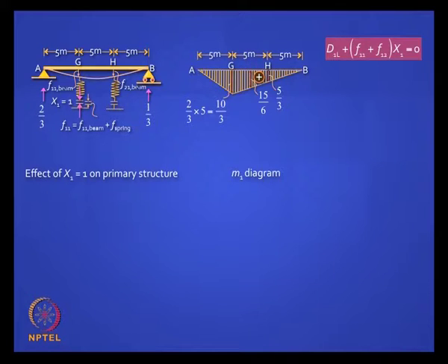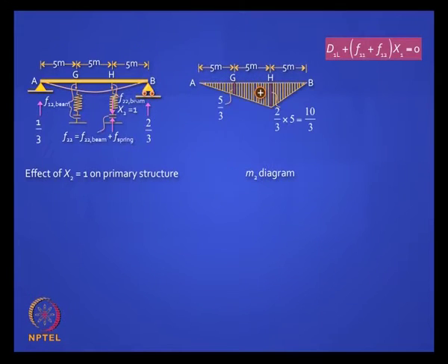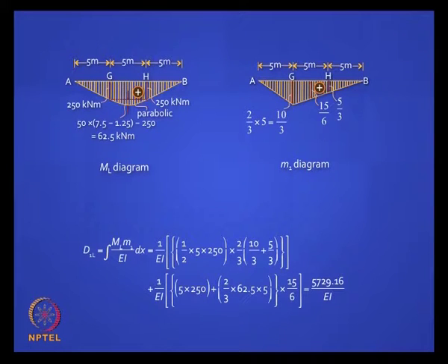That is what we call M1 diagram, and then you pull the other spring down with a unit load, you have M2 diagram, which is the same as M1 but laterally inverted, okay. So you have these diagrams. So can you not calculate d1L? What is d1L? d1L comes from the product of this diagram and this diagram, okay, which you can work out, it is not difficult.